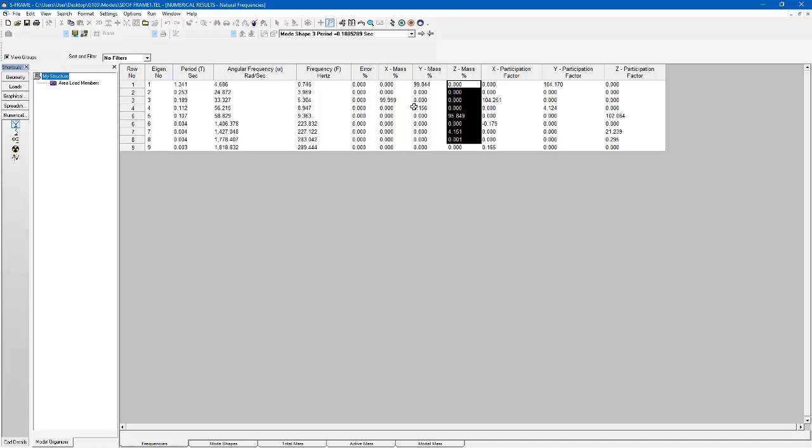And more nodes will actually lead to a more accurate analysis model, but it's not often necessary in vibration analysis, because that will just lead to more complex modes, which are usually higher frequency and therefore not usually the important ones when doing an analysis. But it certainly doesn't hurt to at least explore subdividing your members and understanding those mode shapes, because sometimes the mode shapes can be represented better with more nodes.